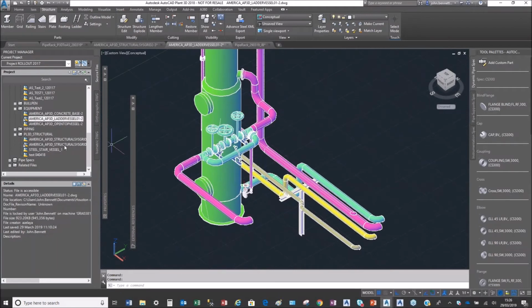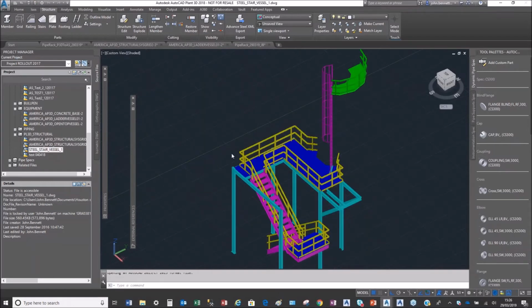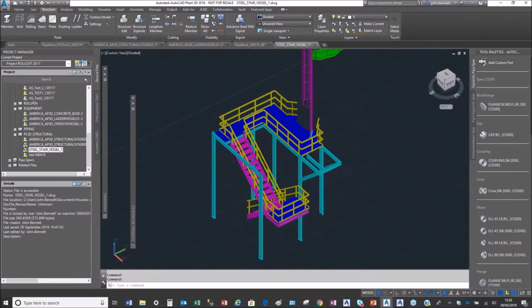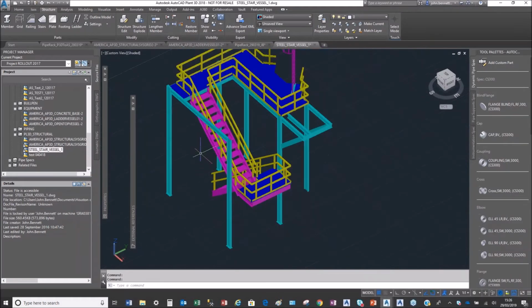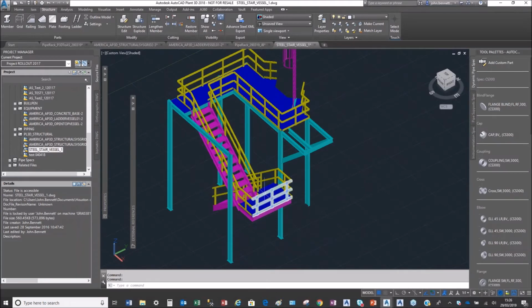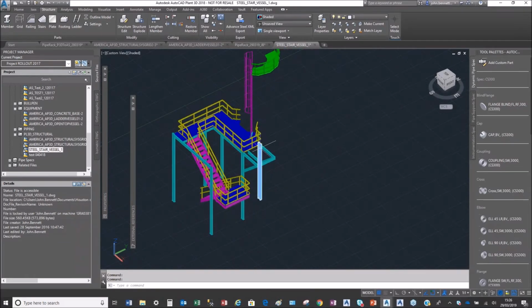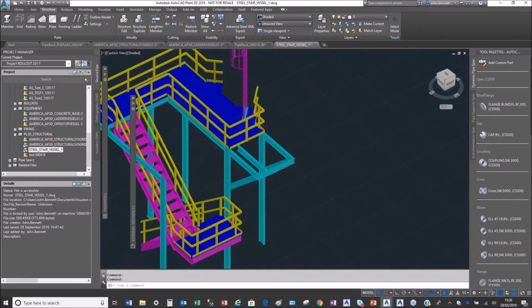So obviously this originally was linked to a steel tower as well that came in and supported round here, and it showed the preliminary of a staircase. Now the two go together, and the stair is fairly rudimentary in here. If I was using Advanced Steel, I would probably want to make use of the stair macro to do this. I probably don't need all this steel because I'm probably going to end up having to move it. I just need to know where the primary steel probably is for the concrete bases, etc. And now it needs to work in with the tank on the side, and any supporting cantilevered structure here.